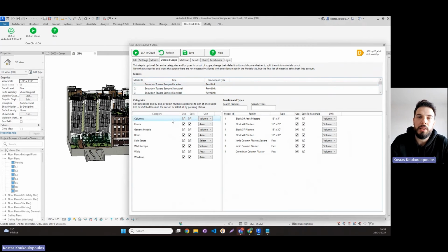And then once you export an object as a whole object, like you export X square meters of external wall, then you can look for wall constructions, which are ready-made assemblies that we have prepared, or that you can also have your private library with such constructions, and map these composite solutions to these Revit objects. And in some cases, there can be also EPDs from manufacturers that refer to more composite systems for specific material categories and solutions. Yeah, so keep that in mind.